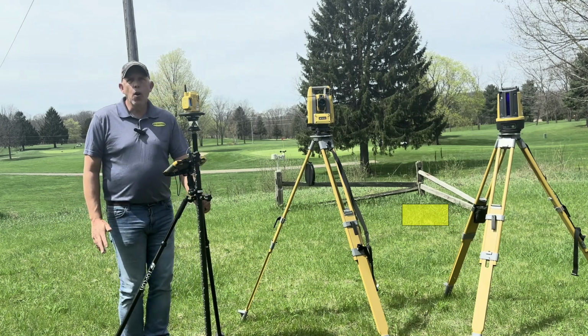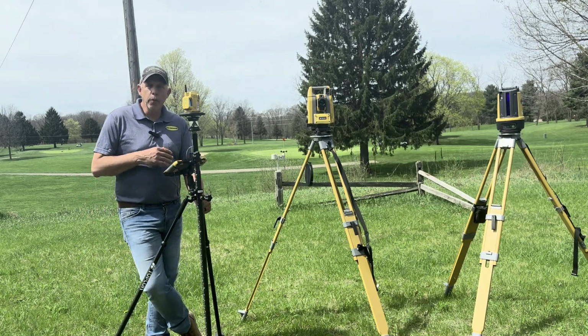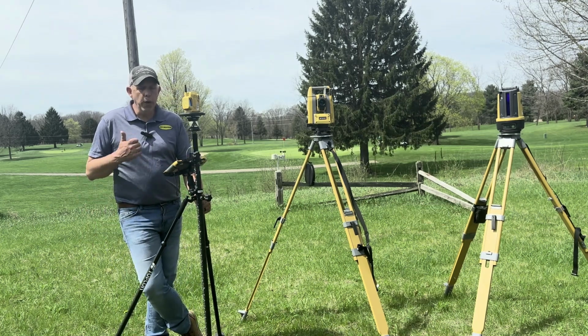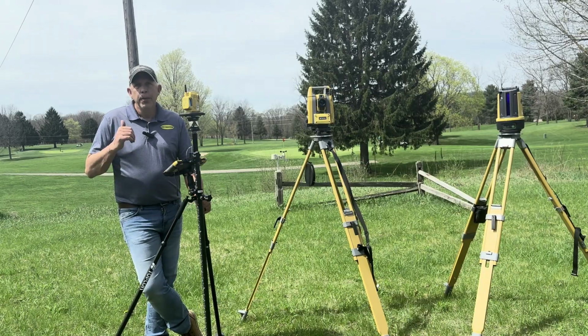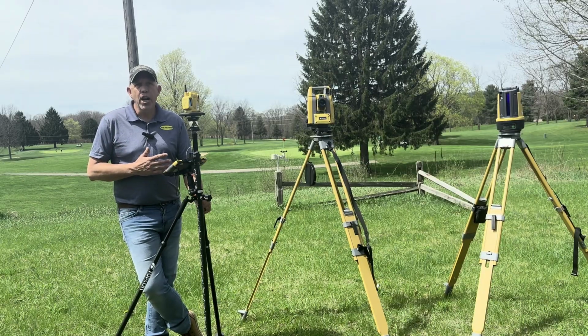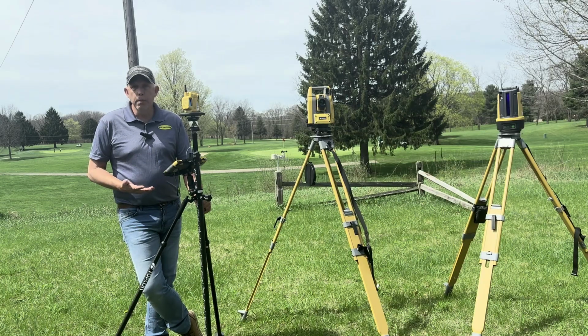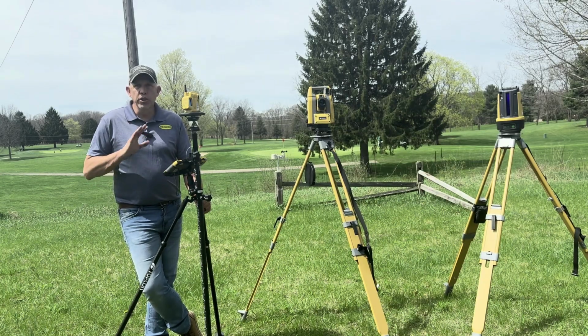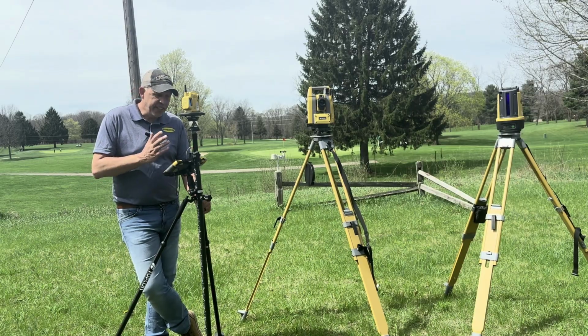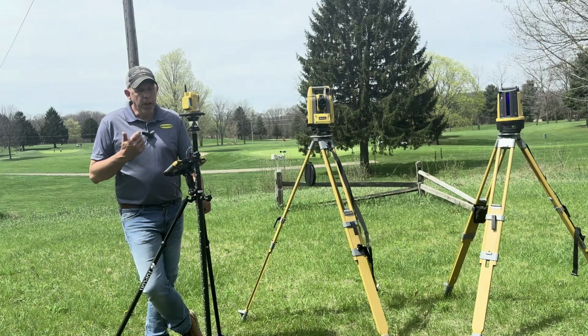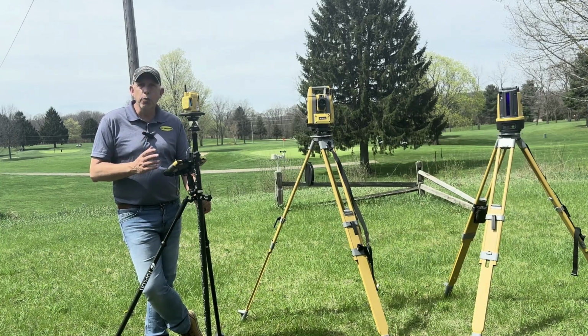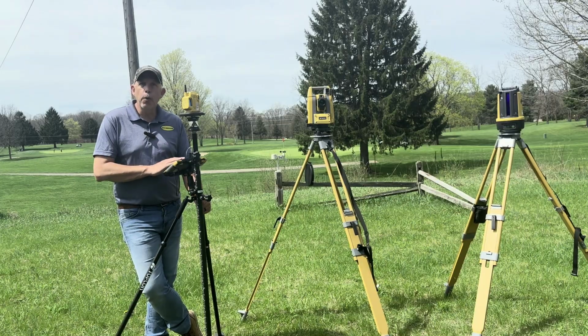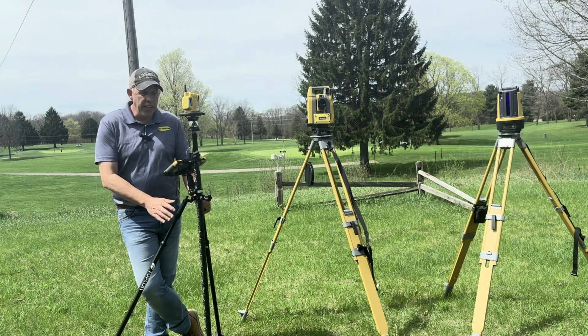Okay, so now we're going to go over bringing a job in, and we can bring a job in one of two ways. We can do it with a CAD file, or we can manually draw the job in. Whenever applicable, I like to manually draw the job in because it will tell you it closes. You know all your measurements were correct, and it does not take very long. We can also bring in a CAD file and just turn off and on layers we don't need and select points on the layers that we want to lay stuff out on.